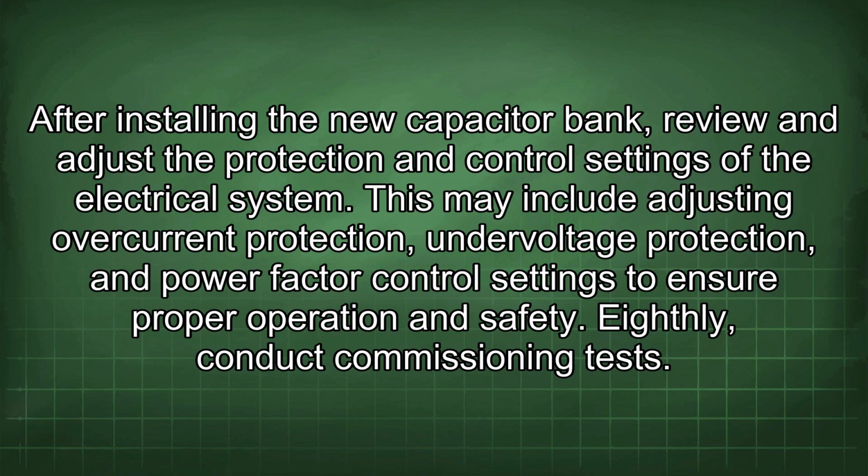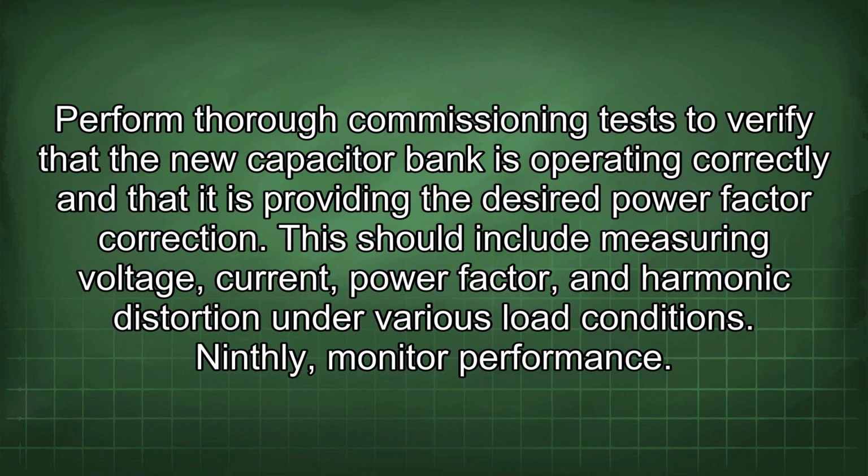Eighthly, conduct commissioning tests. Perform thorough commissioning tests to verify that the new capacitor bank is operating correctly and that it is providing the desired power factor correction. This should include measuring voltage, current, power factor, and harmonic distortion under various load conditions.